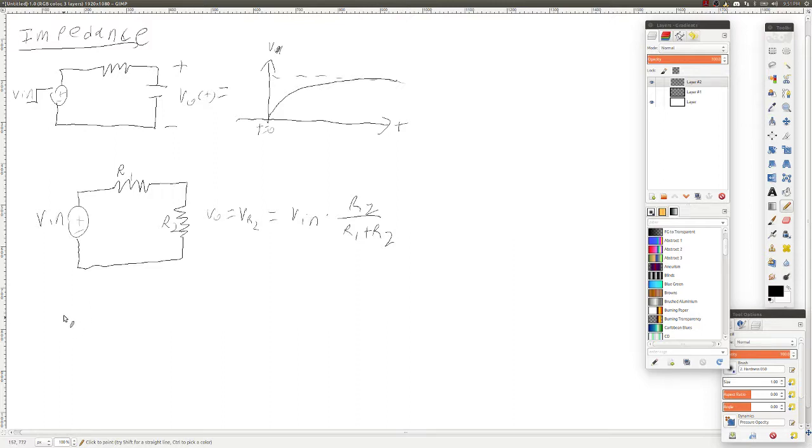What if we could translate this simple method to work on this circuit as well and give us the information about the output voltage? Well, we'd be able to skip all the differential equations first of all. But to do that, we need to know the resistance of a capacitor. The issue is that a resistance is fundamentally a property of a resistor. There isn't a resistance of a capacitor, but there is a unifying property, which is called impedance.